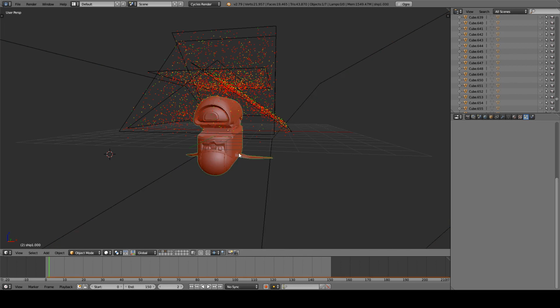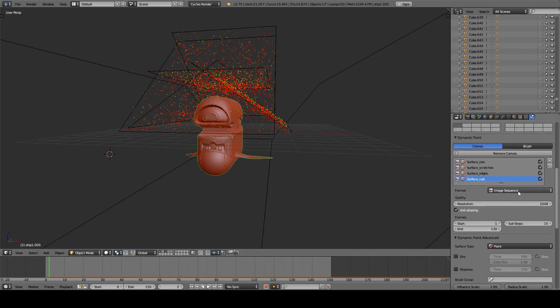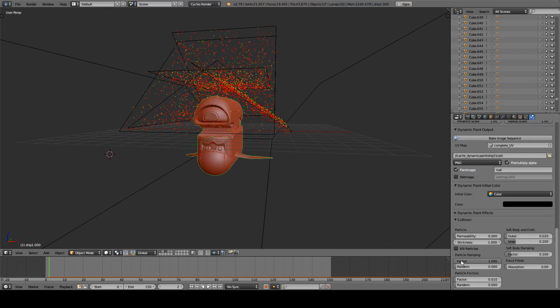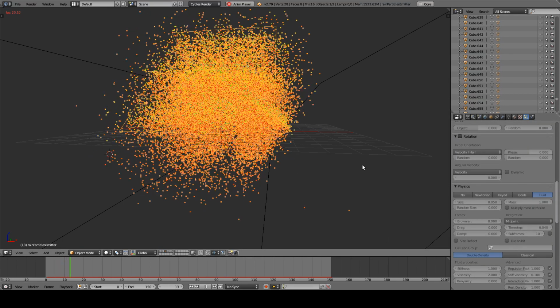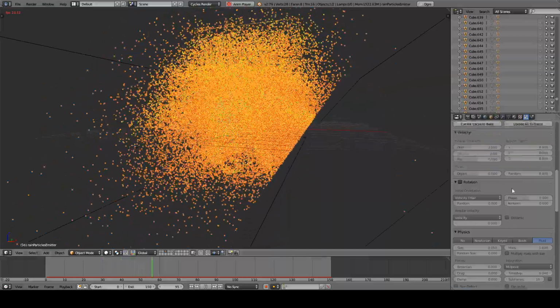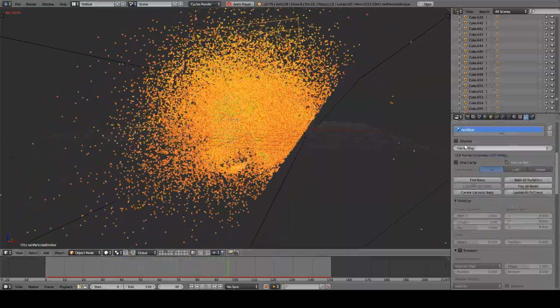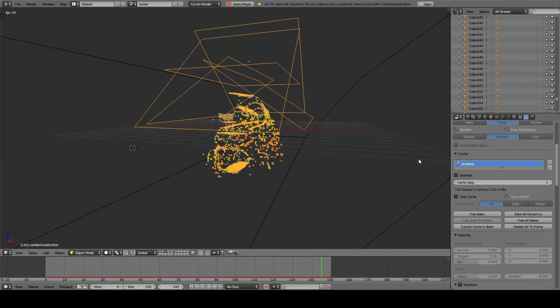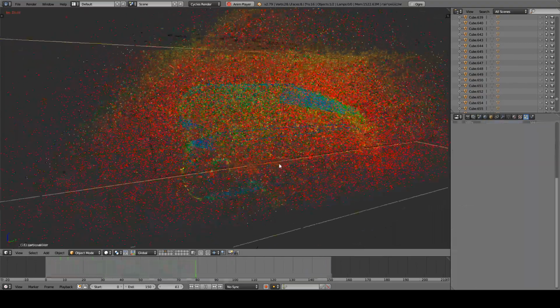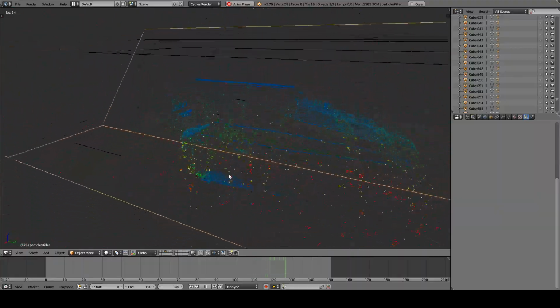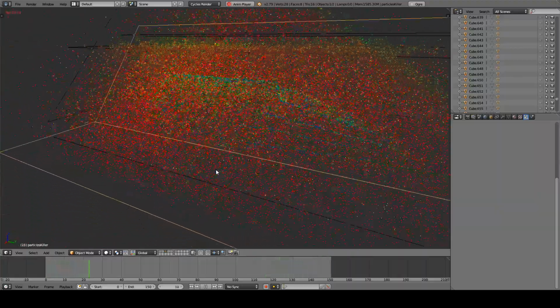You want to make sure that the rain flows nicely on the surface, so be careful with the damping and friction of your surface. You can then launch the simulation. I recommend always baking it somewhere to verify the first time that your particles don't do anything silly. In the end, it should look something like this. You can already see the general flow and the crevices where particles get stuck.